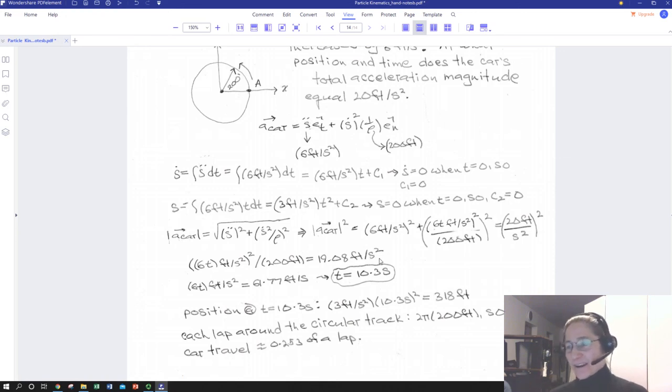That is it for our whirlwind treatment of examples of cylindrical coordinate applications, derivation of tangent normal being really similar to the r theta relationships for cylindrical, but with the twist of your radius term changing with your position on the path and therefore being expressed as the radius of curvature in terms of that d theta ds little expression.